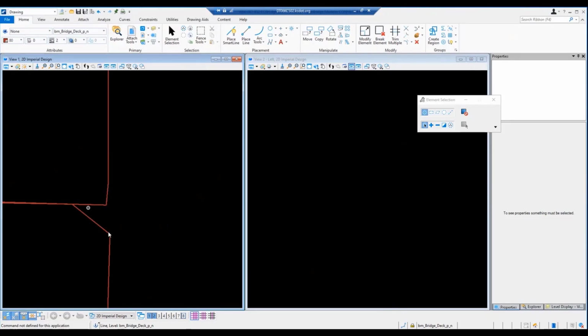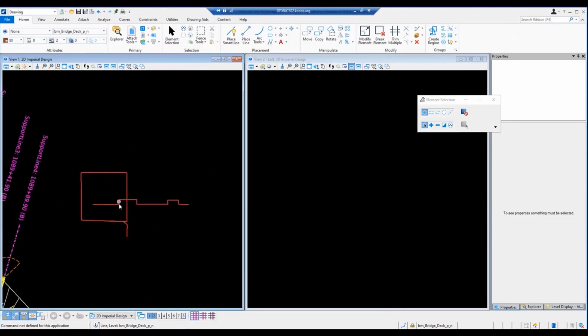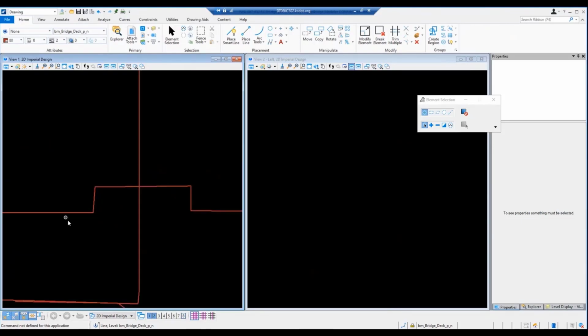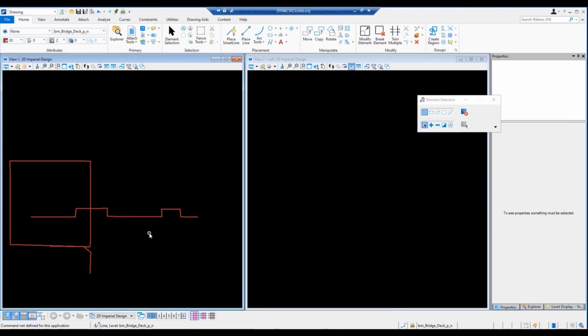So essentially, all you would really have to do is along your bridge deck, select this line that's into and out of the page, copy that to a different file, move it up 3/4 of an inch, and then everywhere that you needed an interior post, step it up 10 inches, go over 3, step it back down. And I think that might be the easiest way that you would be able to put in your 10-inch corral rail posts. But it's just a thought.